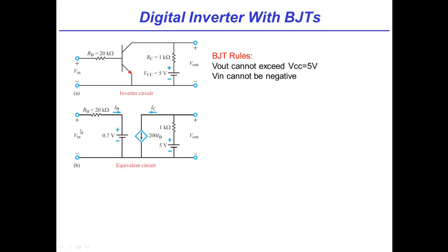All right. Anyway, we're going to stick in our equivalent circuit, and you see that Vivek has provided us with a beta of 200. You'll also notice that the VBE is 0.7 volts. That turns out to be a fairly fixed value for silicon. The value of VBE is to a large degree determined by the material of which your transistor is made. For silicon, it's about 0.7 volts. For germanium, it's about 0.3. There are different values for different materials. Without getting into details, I'm going to guess there's a reason this number is very similar to a PN junction diode forward voltage.